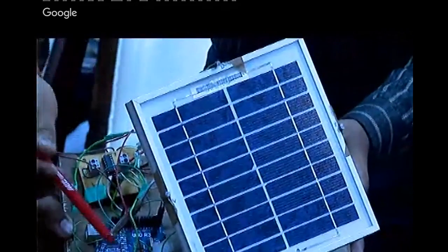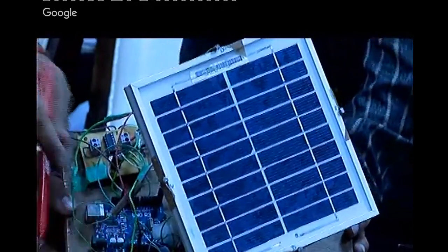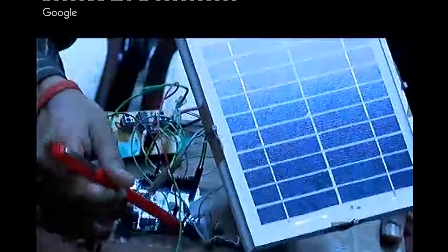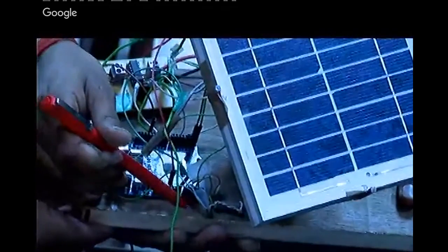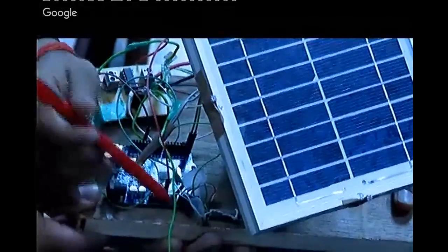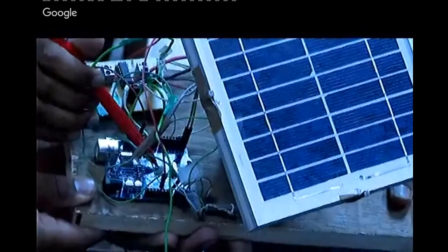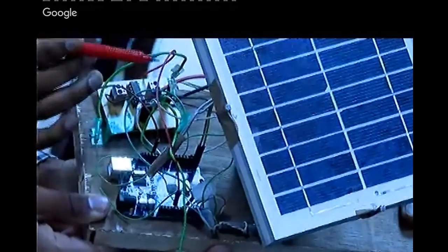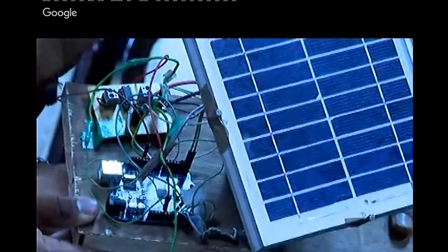It will take the signal via a potential divider circuit at A0, A1, A2, A3. These are the input voltages given by the LDRs, and they are sensed by the Arduino microcontroller, which continuously checks which LDR has the maximum voltage and rotates toward where the light is maximum.